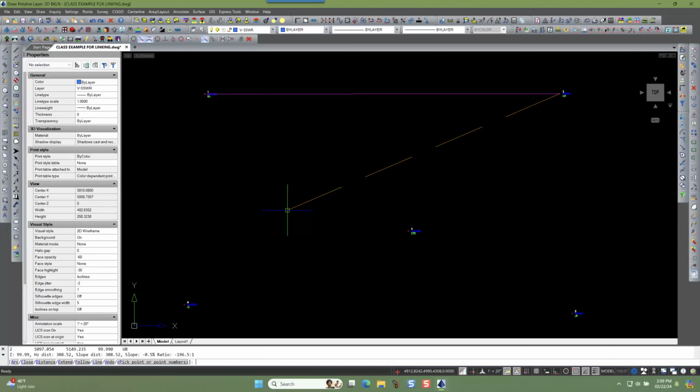But if you click somewhere, let's say I'm going to go from point 2 down to point 3, but I'm going to sort of zigzag my way to it. So if I pick something that does not have an elevation, let's say I pick here, notice it temporarily sits there and says, all right, what's my elevation? See, it read it as 0.0 in the line above, but I can say, well, let me go to the next point or the elevation. I'm going to interpolate along the way.